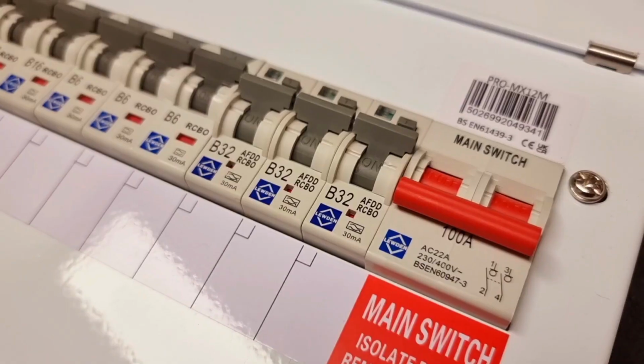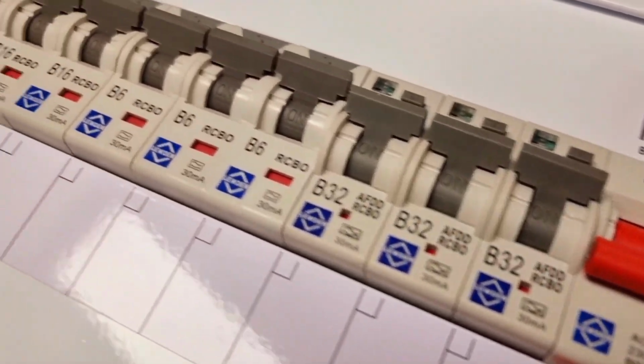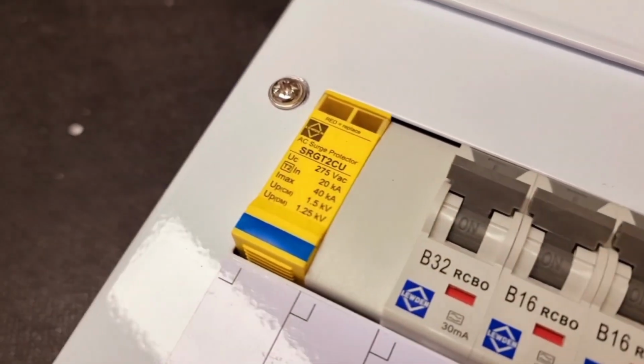However, even with all of this, there is also one more type of protection provided by an AFDD, and that is overvoltage. If the AFDD sees a voltage over 275 volts, it will again disconnect the circuit. So this leads some to the natural question, does that mean if the AFDD provides overvoltage protection, I don't need to install a surge protection device?